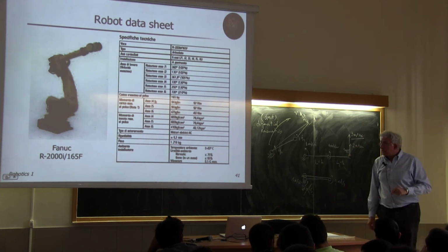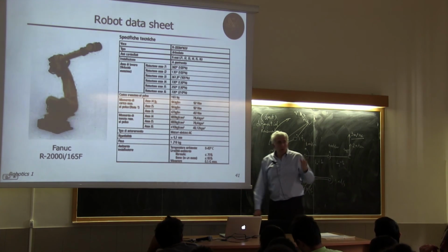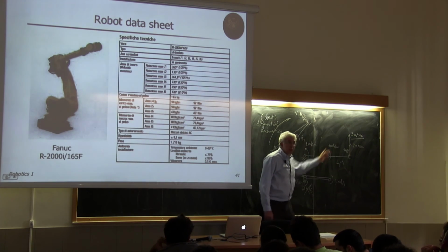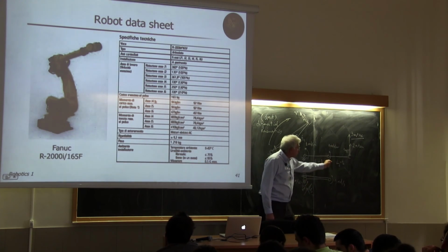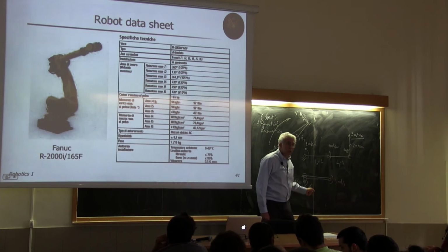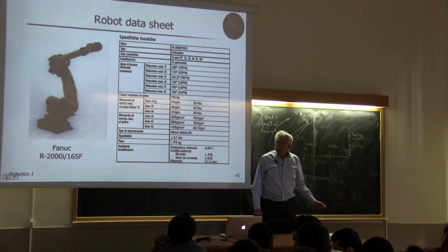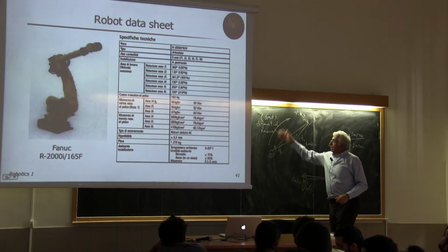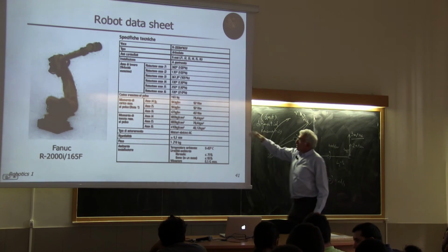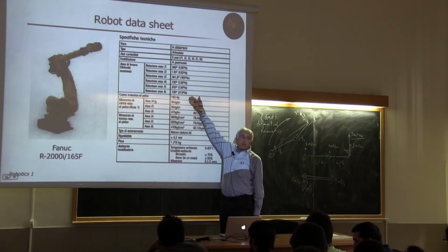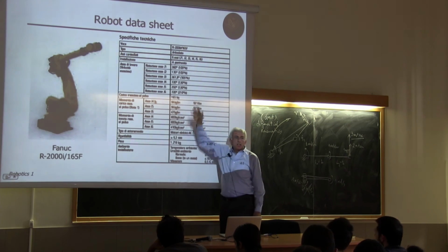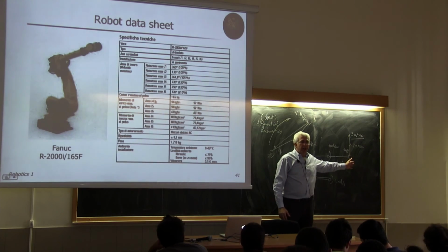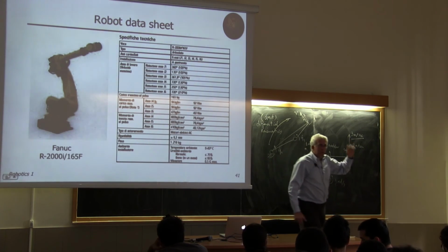But at this point, we'll make use of the so-called Jacobian matrix, which changes with the configuration. Exactly while the result changes here, not because we are changing the joint velocity, but just because we are changing the configuration. Okay? Now we will come back to this differential kinematics, direct and inverse, but for the time being, the presence of this maximum value is just a generic indication of how fast you can go with your end effector. Okay? Just this was my warning.